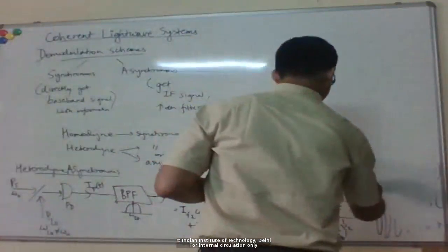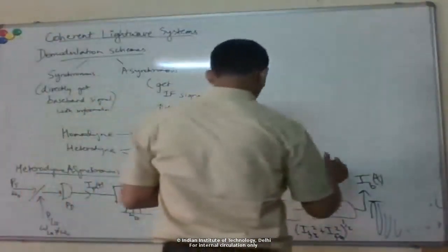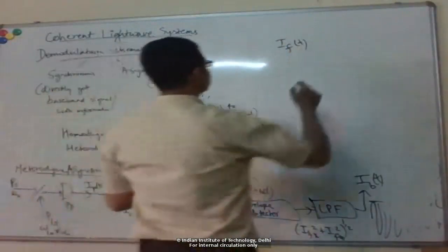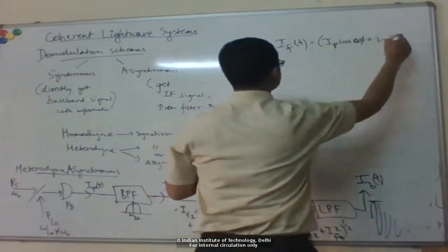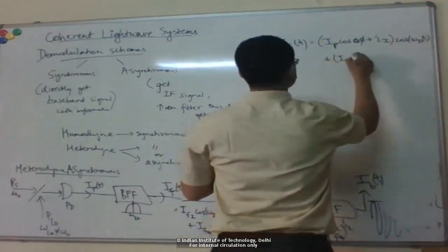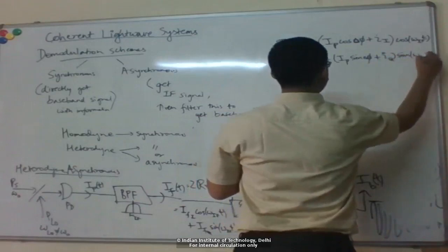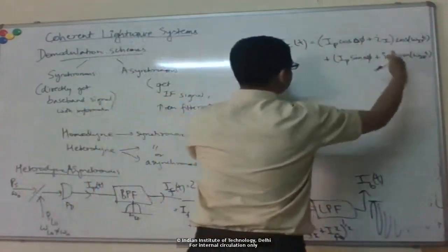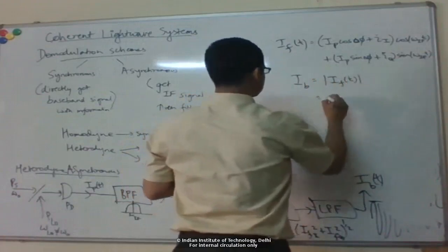Okay, the final baseband current that I get, again I can write this current after the bandpass filter as the in-phase component with noise plus the quadrature-phase current with its own noise. Then basically the envelope detector just takes the time independent part.